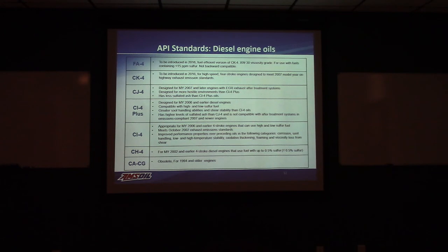There is one little change here. Now we see on the top here an FA4. What the heck is that? I thought C was the indication of the diesel category. Well, that FA is a little diversion. Basically, they're looking at the same type of concerns, the same type of issues, directed towards the same type of applications. However, the FA4 deals with oils that have a very low dynamic viscosity, and that's something new that they're looking at.